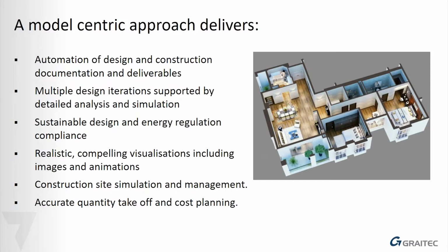We can even start to look at using BIM to actually look at the logistics of site construction, making sure that we don't build the show homes in such a way that we can't get onto the site until the show homes are finished, because there'd be implications of where we actually put in areas, where do we actually put our stores on site, where does all our site equipment live. That's obviously going to be the last plot of land and last area that we can actually build on. How do we actually manage all that?